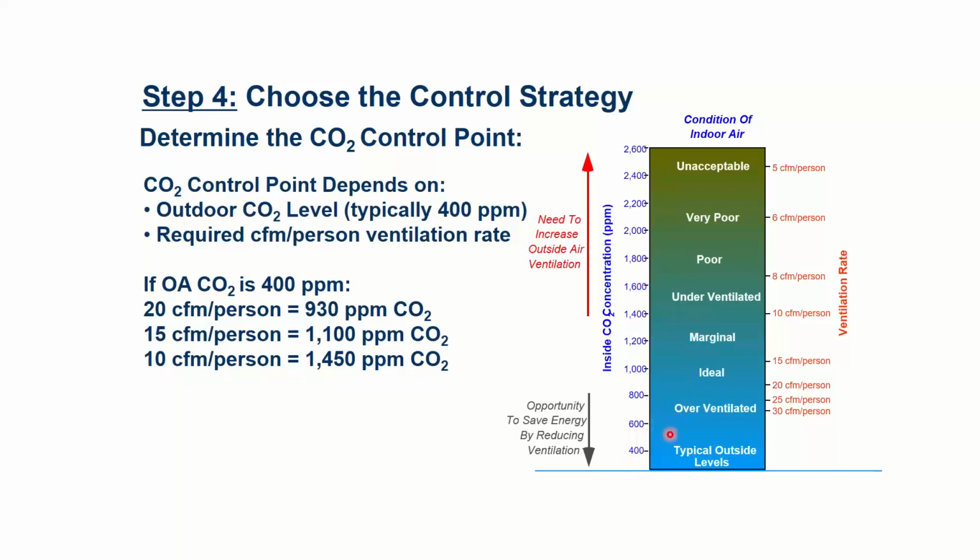If you're down here and you're seeing numbers like this, it's either in economizer mode, which is then it's fine. I don't care if it's overventilated during economizer mode because I'm getting free cooling. Or if it's not economizer mode, meaning it's a cold day outside where I need heating, or it's a summertime day, then I see these low numbers, I know that I'm actually overventilated.